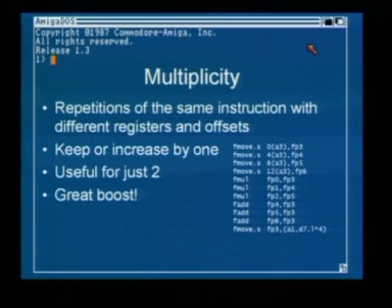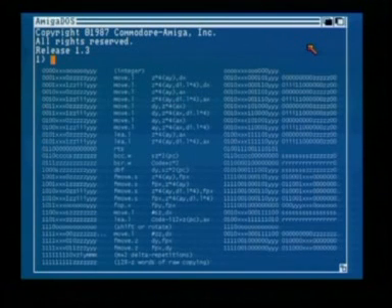So if we scroll back to this list here, you can see that down in the delta repetition instruction, there are 4 bits called X, Z, I, and Y. And if you look at the similar fields in the rest of the instructions, there are some X and some Z and I and Y. You can see that the beginnings of those are exactly 3 bits spaced apart.